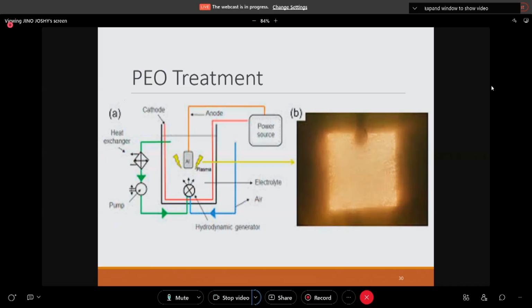In anodization, we take an acidic environment, and once electricity is passed, metallic dissolution happens. Metal ions start dissolving, and from the electrolyte there will be splitting of species. H2O will be split into H+ and OH- ions, and some other chemicals may also be added. The OH- ions move towards the anode and react at the interface, and coating formation happens.